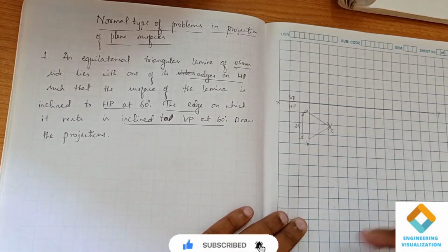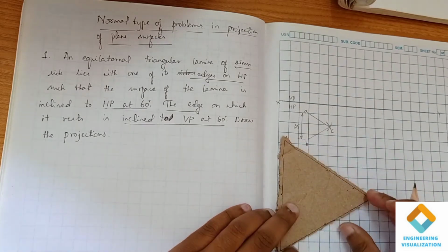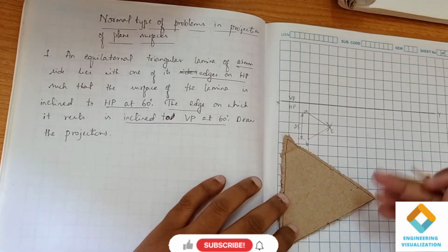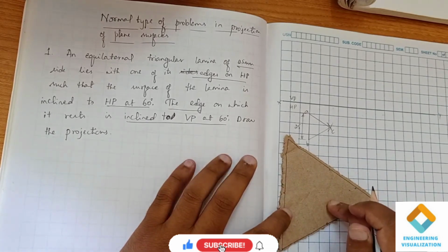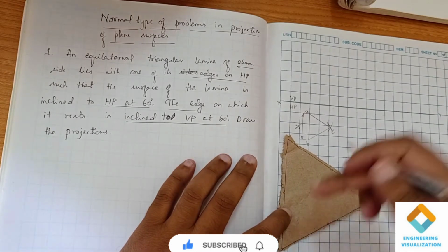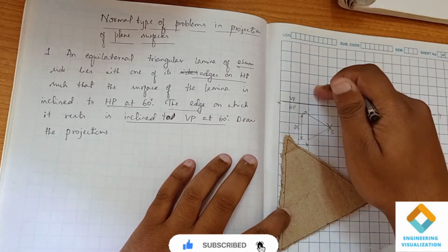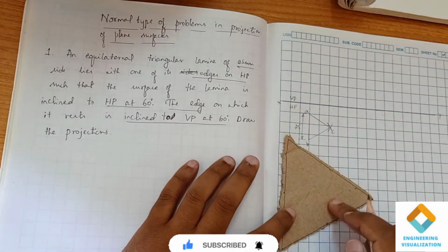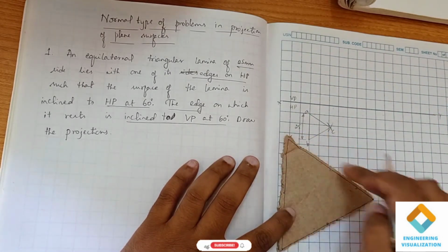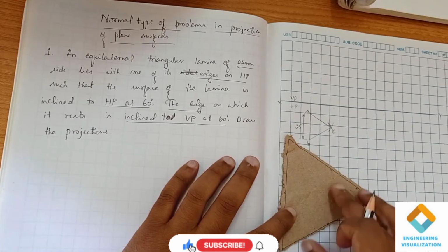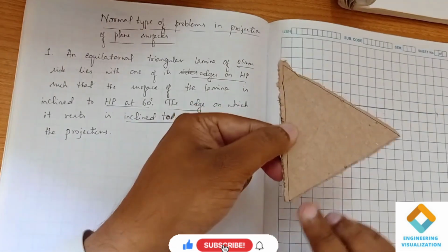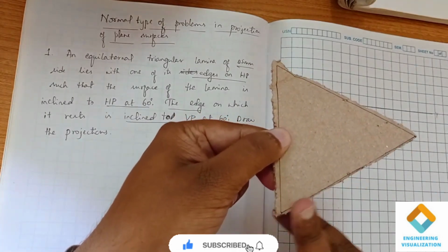Now we have to draw the front view of it. We have placed the triangle like this, just in order for you to understand the first position, right? We have to draw the first position, top view and front view. We know that the front view will be lying in the VP plane. So in this top view we have got the triangle of dimension 25. If you are looking at this triangle from the front, you will be able to see only this edge, that is BC.